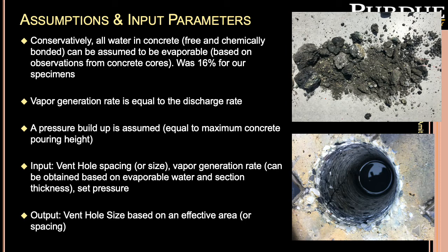After we had tested our specimens and subjected them to standard fire curves, we cored concrete out, and what we observed was that the cores were highly disintegrated, and we felt that it was reasonable to assume that you would lose all of the water in concrete under these circumstances.